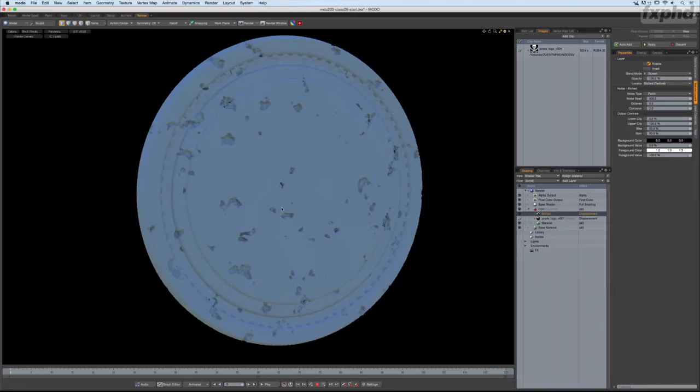I've got to apologize. I'm doing the screen recording and doing some rendering with some displacement maps, and my computer's getting bogged down. But to really get the result that we want, we're going to change on our etched texture the background value to -100, not plus, minus -100. There we go. All right, so now these holes are going to go deeper. Yep, now these holes have been pushed back another 10 millimeters, and I'm going to put my foreground value to 0. And we should see things start to unfold the way we want.